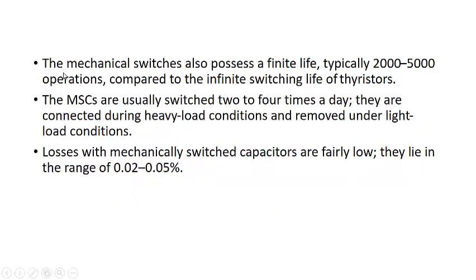Now, the mechanical switch also possesses a finite life, typically 2000 to 5000 operations. Because of wear and tear, there are only up to 5000 operations. So they possess a finite life as compared to the infinite life and infinite switching of the thyristors. The mechanically switched capacitors are usually switched 2 or 4 times a day. They are connected during heavy load conditions and removed under light load conditions. So usually they are not frequently switched on and off.